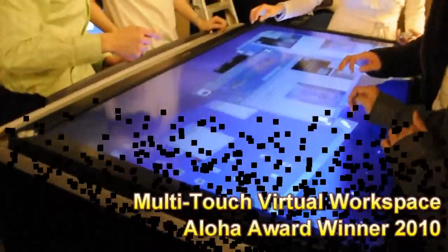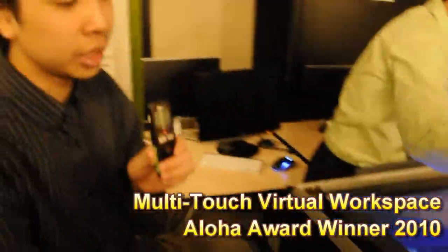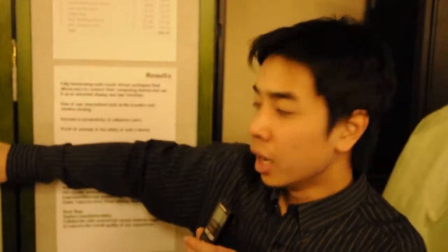The technology behind it is actually a rear projection TV. We've modified it with 1 laser on each corner, 4 in total. These lasers project a plane of laser light above the surface of the screen. When your fingers cross this laser plane, light is deflected downwards towards the camera and picked up, and we do some image processing to find the corresponding X and Y coordinates.